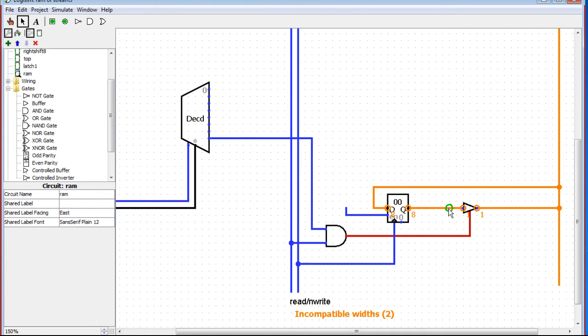Because you can't just connect things directly to the line here, because what if something else is trying to drive this line and this is also trying to drive the line, then you've got a short circuit and fried components. So you put this tri-state buffer in here, and now it allows you to selectively connect different nodes in your network to each other. So that is for the read portion of our program.